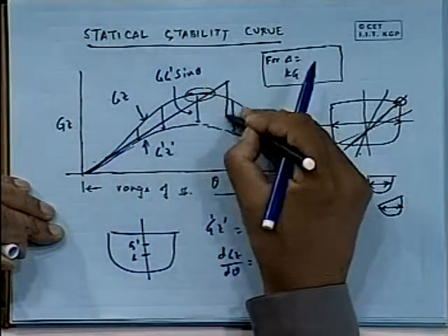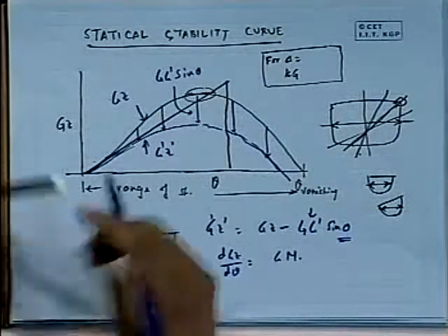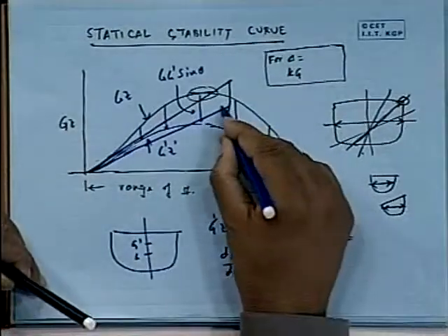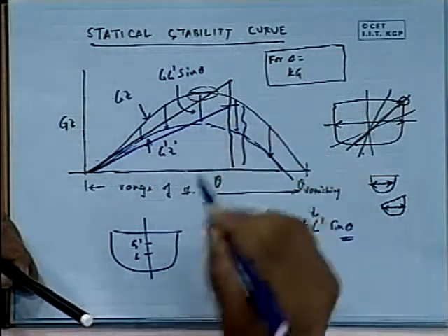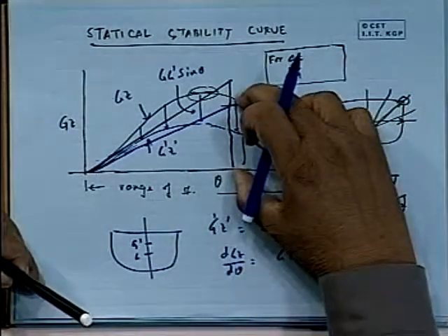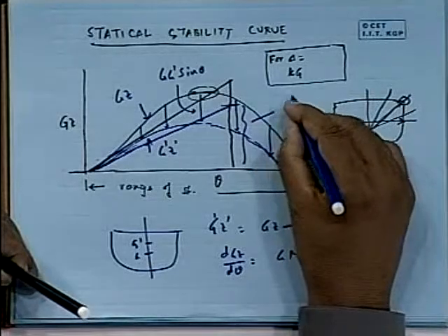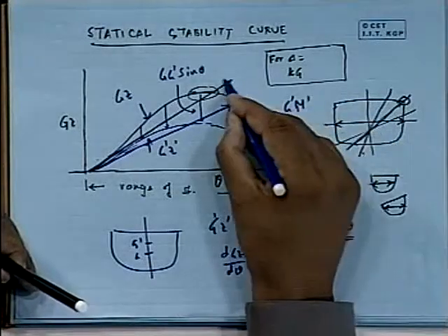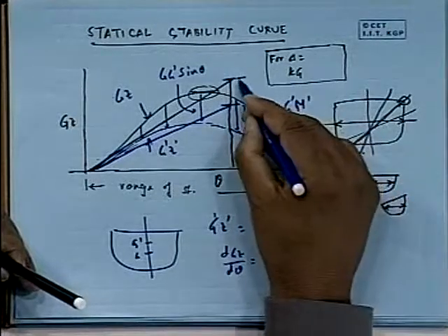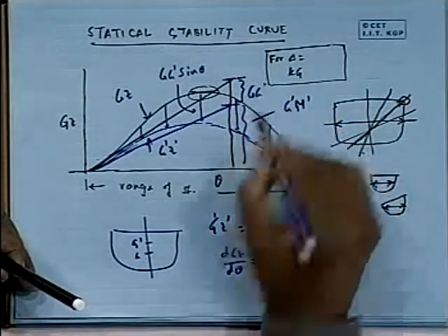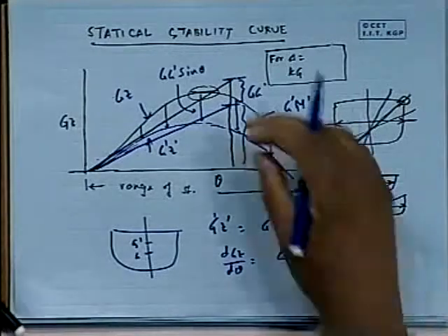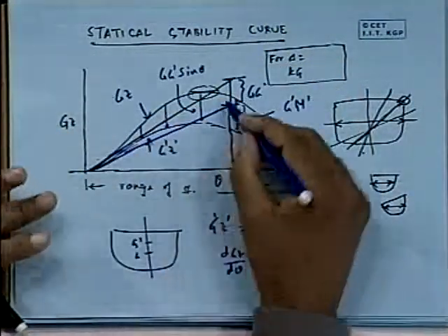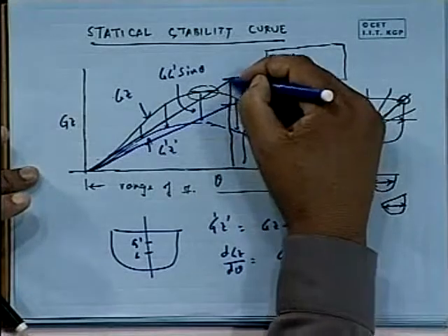Say if I take it 1 radian here, now the reduced one becomes this one. So this becomes my new GZ, this distance. That is GM, no sorry, new GM, this is my old GM, and therefore this is my GG dash. Again it makes sense, because if you look at that, it basically makes sense that you have just pulled it down.